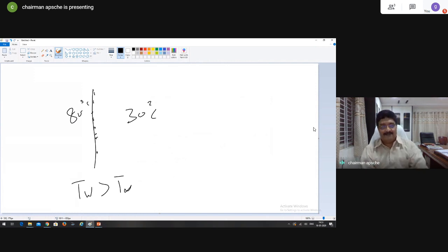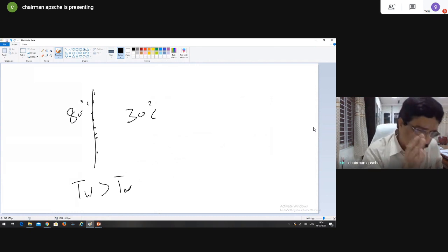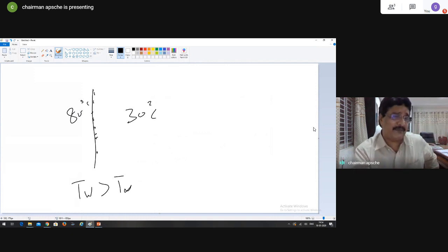So this becomes lighter. This lighter fluid molecule would like to move vertically. Now, can it move up? No, it cannot move. Though it has lost its density, it is sitting pretty in the intricate gaps of the surface. Even for a smooth surface at a microscopic level, you have irregularities, and also the heterogeneous friction, wall and molecular friction. The molecule has a certain viscosity, and therefore it is sticking. Though it has acquired the temperature of the wall, though it lost its density, it cannot move up because friction prevents it.